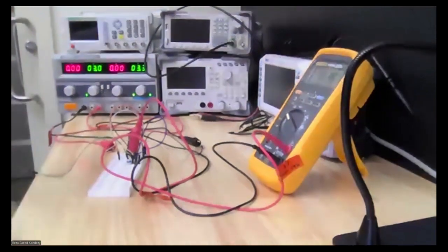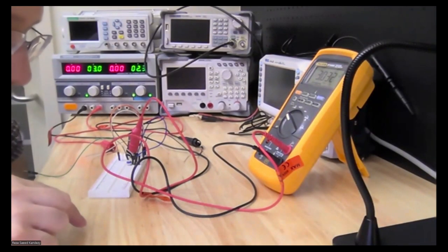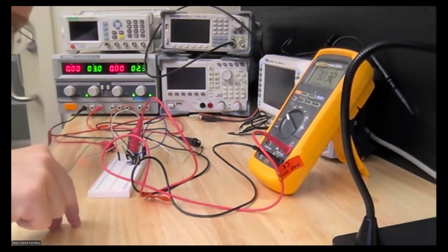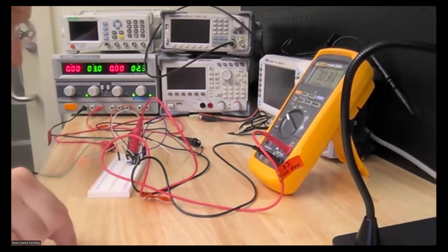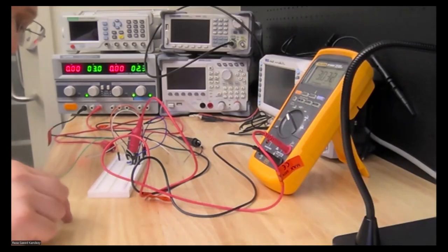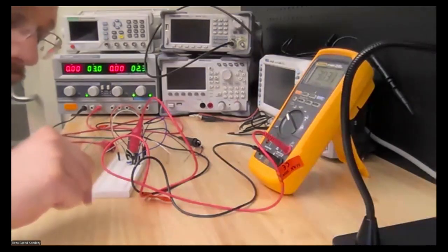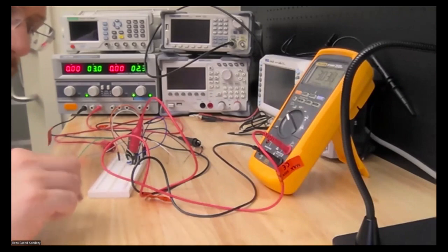Okay, and I'm gonna apply the value. Now, what I read is 3 volt across the collector and emitter. So this is the first vector, the first point in your graph on one of the curves. Okay, so the curve for that specific 10 microamp of base current, the first point on that curve is we measured already the 4 milliamp, around 4 milliamp.